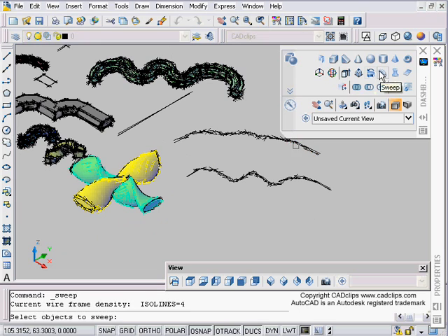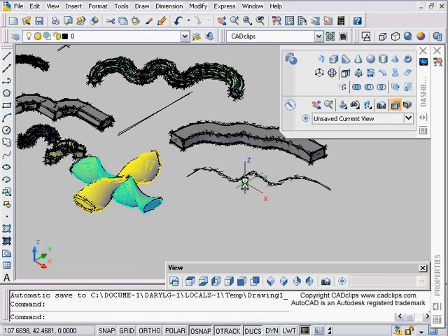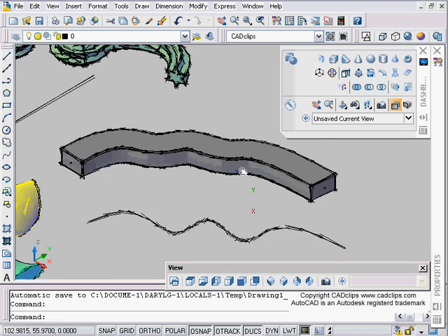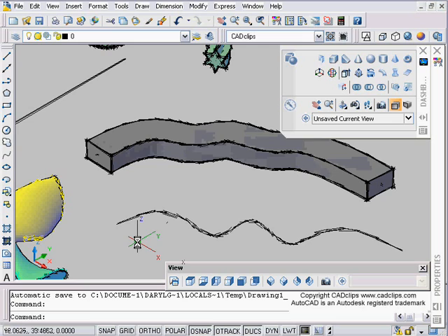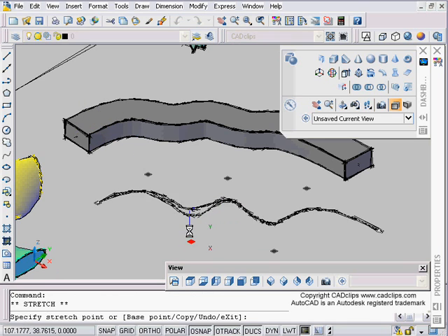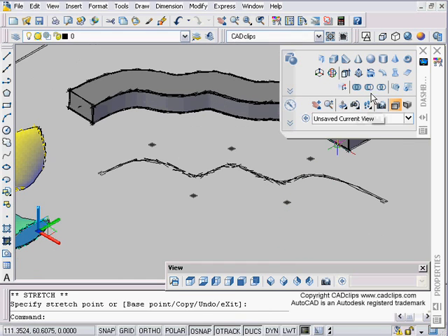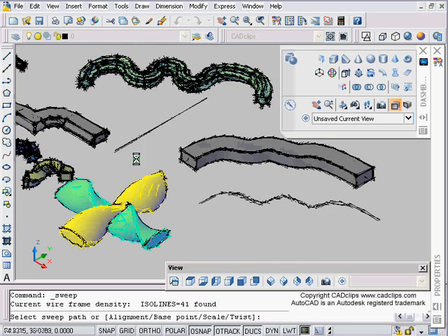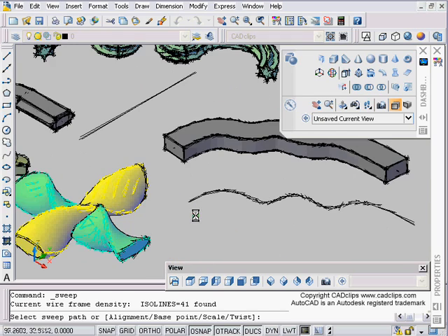Okay, what if we draw just a spline? Let's try this one more time to make sure. This, enter, here, and oh, that time it worked, interestingly enough. So the thing is, you have to be careful if this object is too large and it starts to actually interfere with itself as it goes around the corners. That's where you'll end up with a problem. So that may be the problem with this, is that those curves are a little too drastic. Okay, what if we try this one more time and we pick our rectangle?